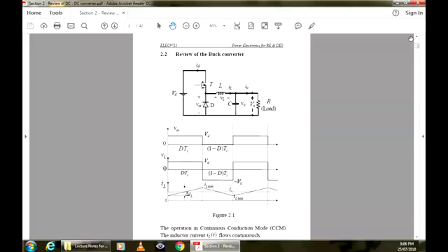What is the voltage across the inductor then when the diode is conducting? When we have switched it off, we assume that the current is flowing here, part of it through here, part of it through here. Anyway, the diode is conducting. So what is the voltage across the inductor? It should be easy for those of you who have done power electronics before. Minus V0, right? That side is positive and that side is 0. Previously this side was negative because V0 was less than Vd. So if we know this time, we know the slope, which is minus V0 over L.